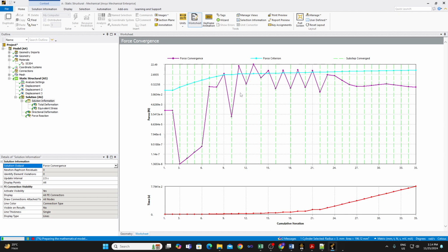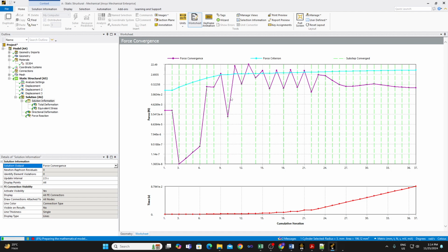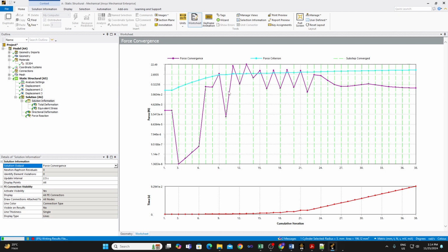Okay. So in nonlinear FEM, the norm of the residual actually needs to be checked against a tolerance, of course multiplied by a reference value. If you have used ANSYS, you would know that. Within the elastic limit, that happens automatically. But when the yielding starts happening, then the solver has to check between two different slopes, and because of that, the residual.